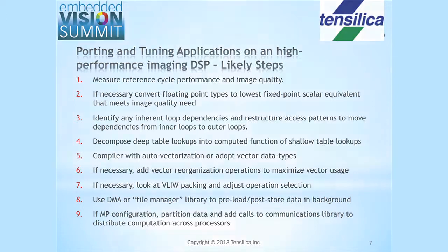But you probably want to have thought about key issues in multi-core. In particular, is your basic strategy to subdivide the images and have each core working on a different sub-image, or to pipeline the computation where each core is doing some stages of computation on the whole data stream? That will help you determine what is driving the optimization of some of the other pieces.